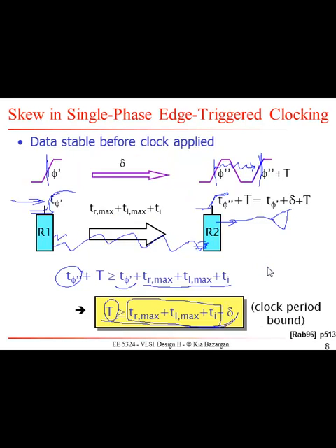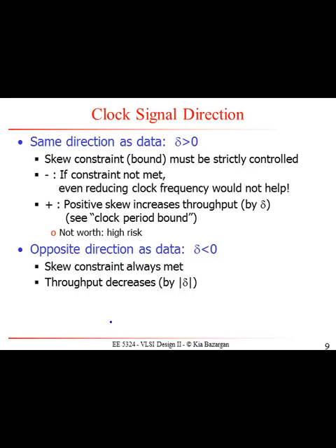It's going to make it go away, but a negative delta is going to make your t longer, which means your clock frequency is now going to go lower. So it's bad for your clock frequency. And I apologize, I think I misspoke. I said that it's good for T, but essentially you're increasing your clock period, which means your clock frequency is going to decrease with a negative delta.